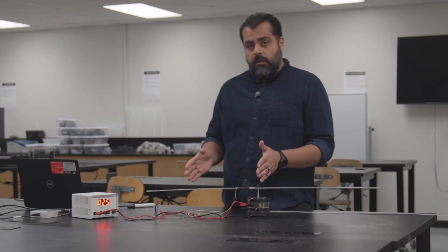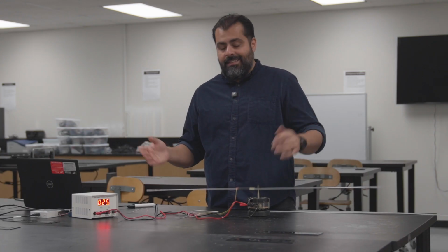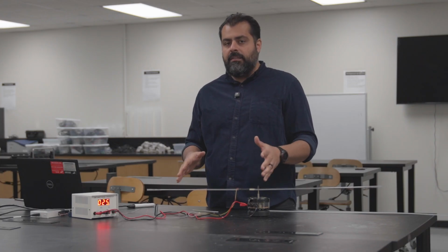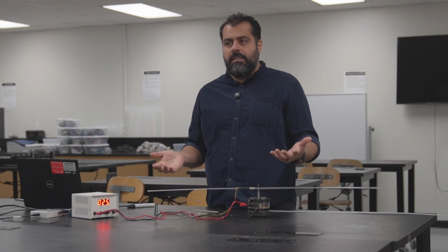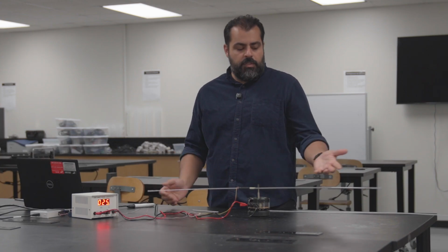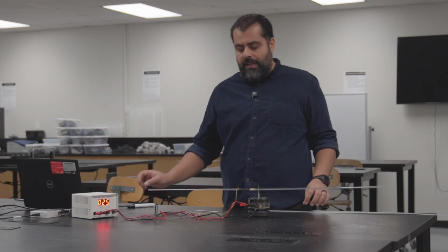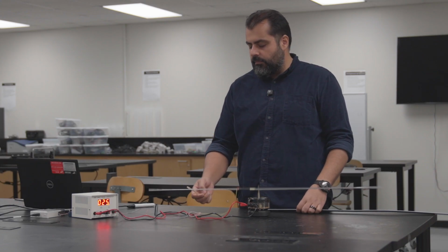We can also do another measurement for this beam. Theoretically, they have to give us the exact same values, but these are two different cantilever beams, and this is experimental work, which essentially means that there is some error involved. If I'm reading 345 here, I might read a different value here. Let's actually do this as well.